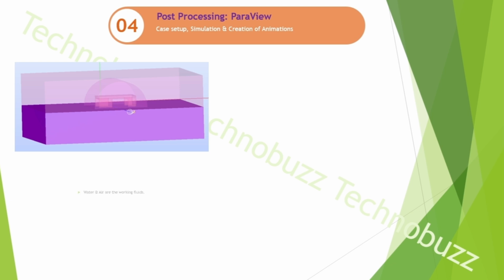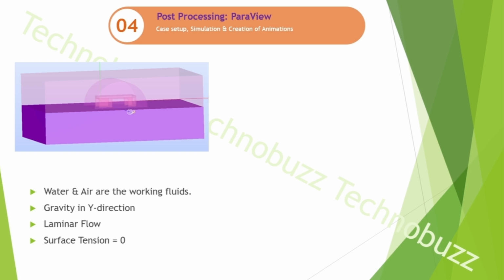Let us see the operating conditions. Water and air are the working fluids. Gravity in the y direction is considered as the domain is created in that way. The flow is considered to be laminar and the surface tension between the fluids is considered to be 0.